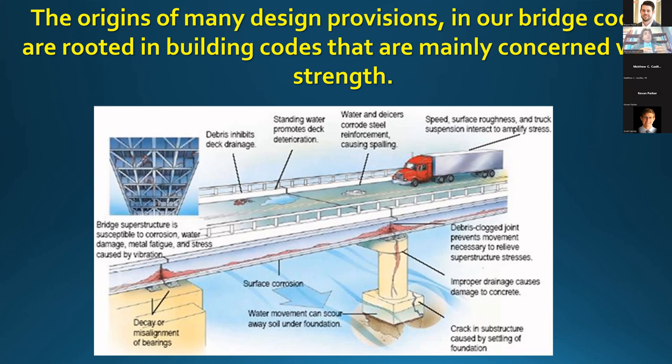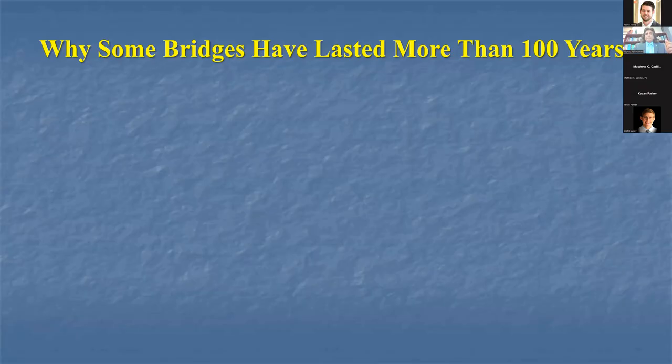One of the reasons that every day it seems like we are developing a new AASHTO guide for this, a new AASHTO guide for that, is because we have taken many items from the ACI and AISC building codes, which are rooted in strength, but durability is what is really giving us a hard time, the corrosion and so on. Those are not addressed through strength. Those should be addressed through life cycle performance, the long-term, cyclic behavior, exposure to the weather elements, and so on.